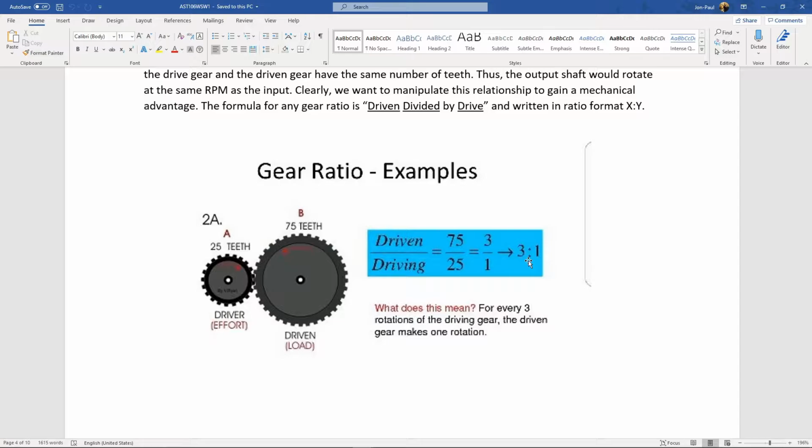which means it got terrible fuel mileage. The new Genesis that I was in not long ago has 12 forward gears. That means the gear ratio in 10th or 11th gear at 80 miles an hour is so low that the engine was at 900 RPM as I was doing 80. That's insane. If I tried to accelerate and didn't downshift, it would go so slow. It wouldn't go from 80 to 85 very quickly. The flip side being, if I can do 80 miles an hour at 900 RPM, I'm going to have phenomenal gas mileage. So things to consider.